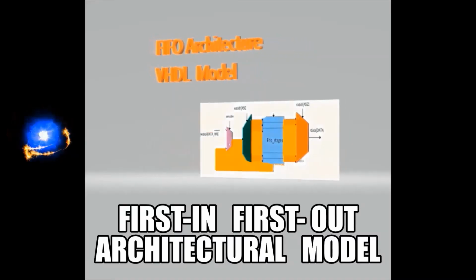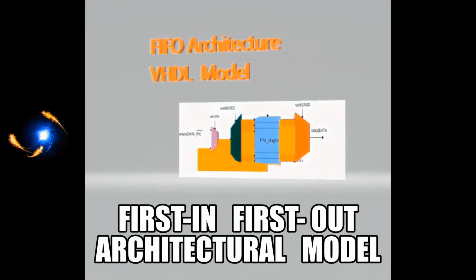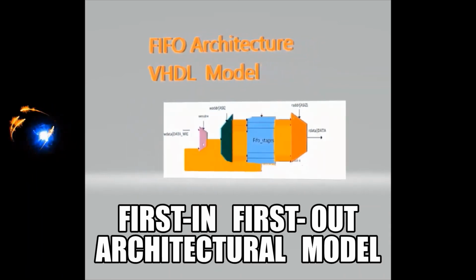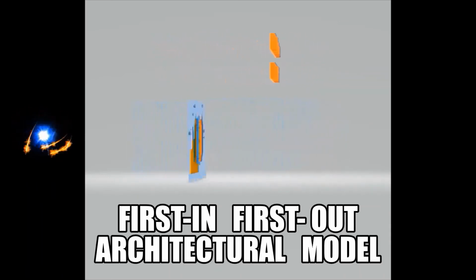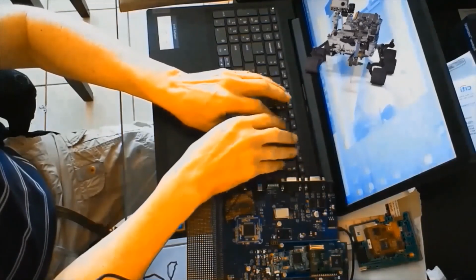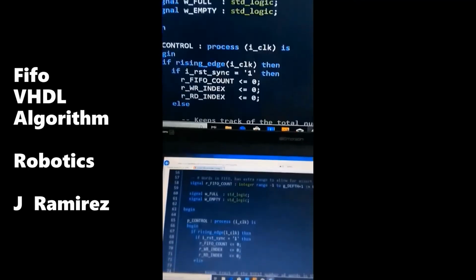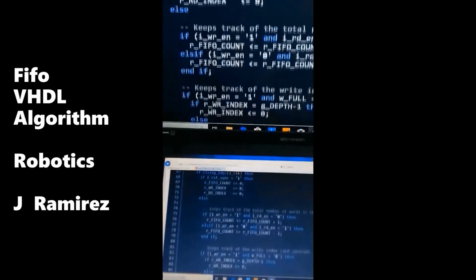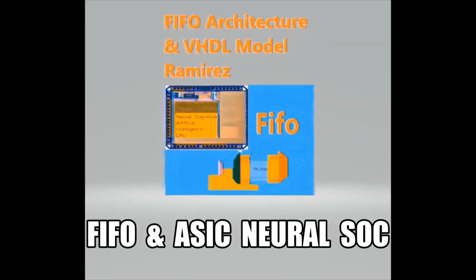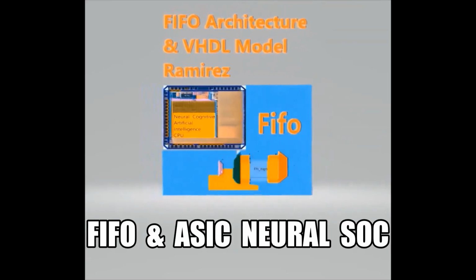In order to write data into the FIFO, first in, first out, first push the data onto the data in bus, and then strobe the write enable input high for one clock cycle. It will write whatever is on the data in bus into the FIFO's internal memory. For writing in bulk, the write enable signal is left high while changing the data on the data in bus each clock cycle.